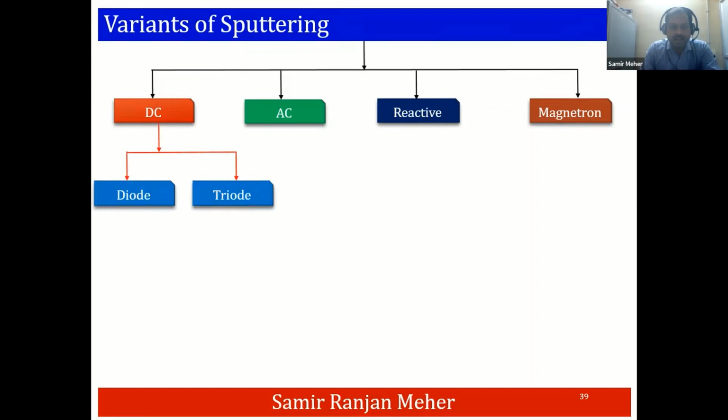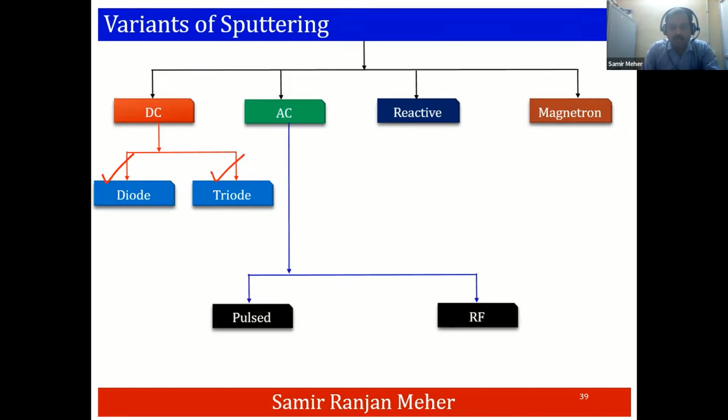Under the DC category, we have 2 things: the diode sputtering and the triode sputtering. For the AC, we have the pulsed mechanism and the other one is the RF mechanism. And the reactive and magnetron sputtering are mostly superimposed on this DC and AC sputtering. Now let us quickly look at the different variants.